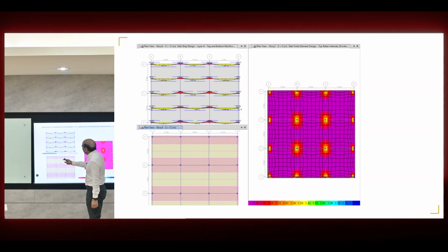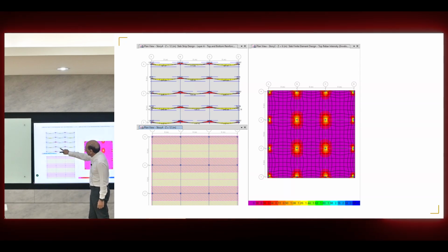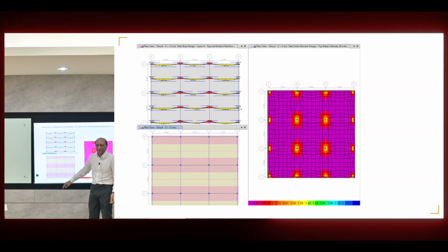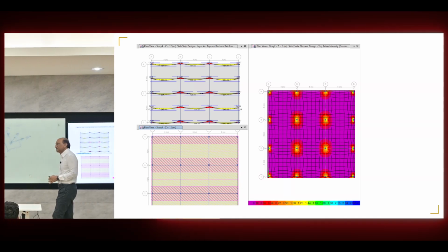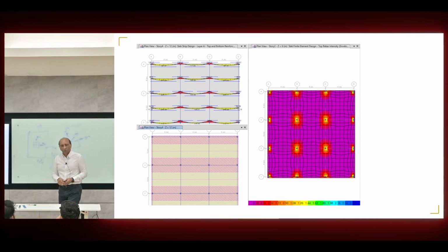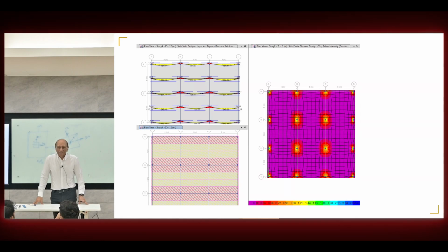So we calculate, and then from that you calculate the top negative reinforcement and positive reinforcement, and then you distribute between column strip and middle strip and beam, and we're done. So this concept is so simple. It just simplified the entire two-way slab system into a very, very conceptually clean and simplified method.